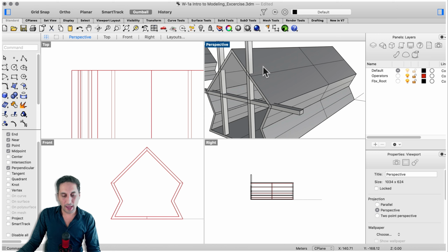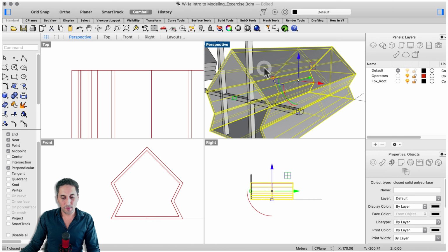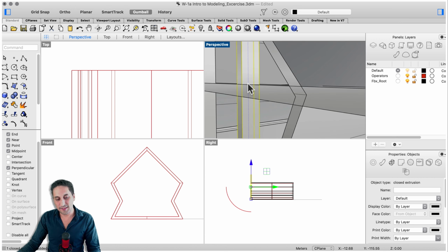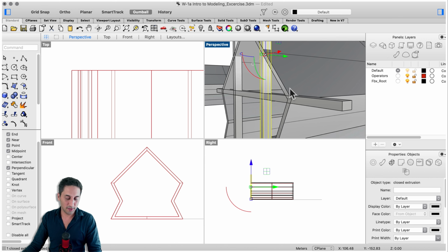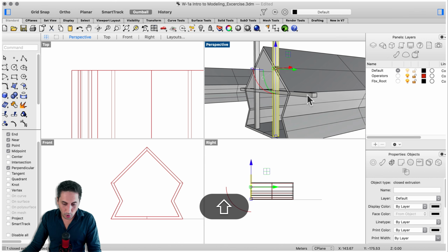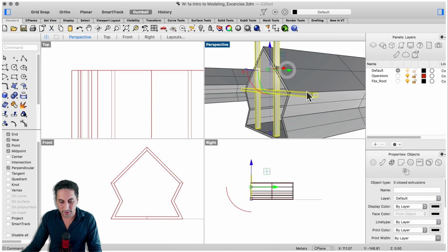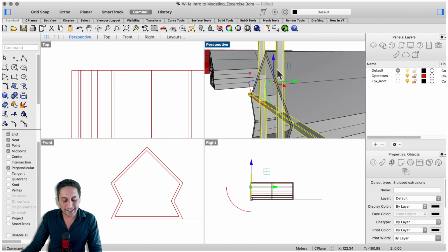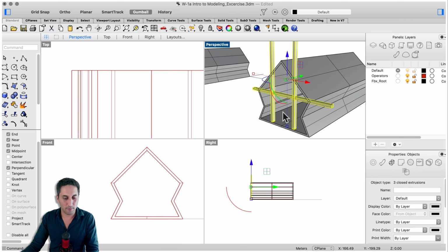Now, a quick tip. We're about to subtract with Boolean operation this from this. Remember that surface and surface is something that doesn't exist in the real world. And sometimes computers get confused when they're occupying exactly the same space, like in one of those sci-fi movies. That is not normal. So it's better if you always think about this and select them and give them a little bit of tolerance. That means let's push them just a tiny bit inward, just so that it's clear to the program what to take out from where.